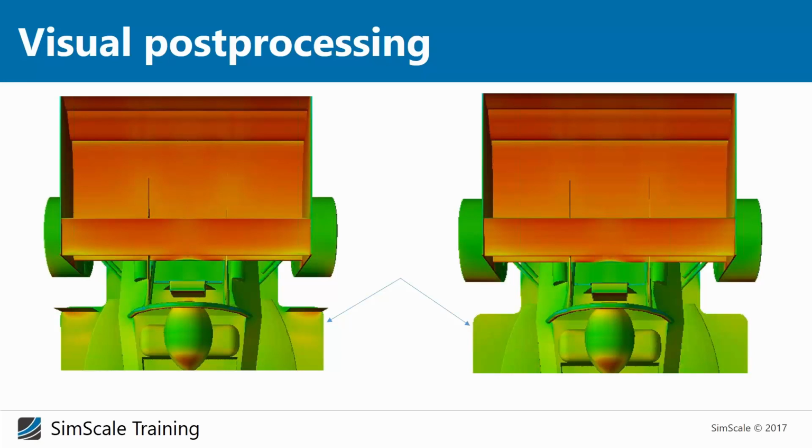And what you see on the left-hand side is that there is a big region of high pressure on the undertray, which pushes the undertray down. And on the right-hand side, you don't have that area. So there is an improvement in downforce due to the pressure difference from top to bottom. And as well, this plate works as a massive gurney, and even on the lower side of the undertray, we have a higher suction effect. And that is pretty cool, I think.